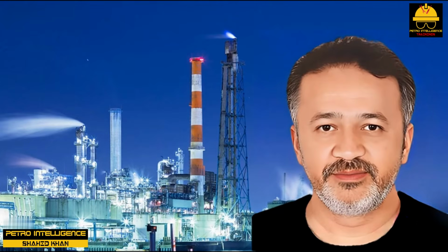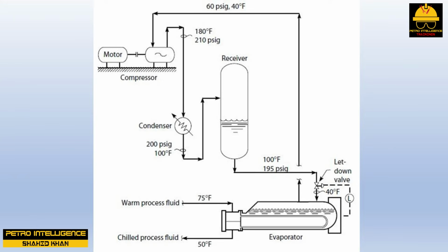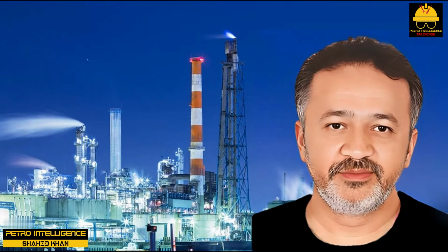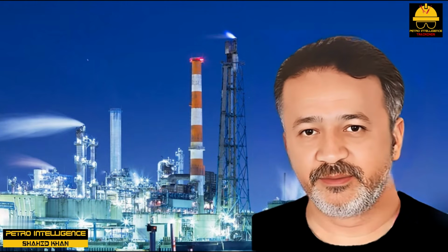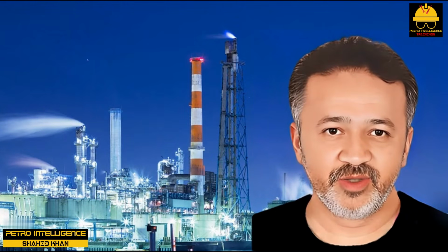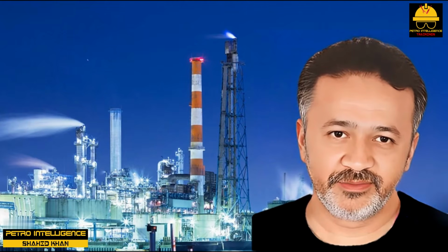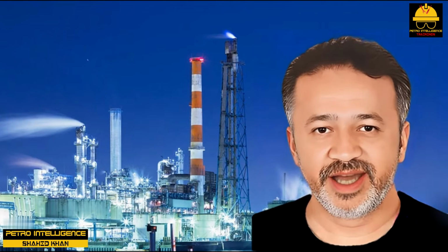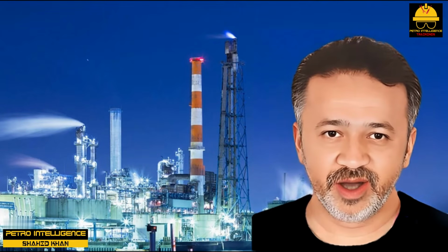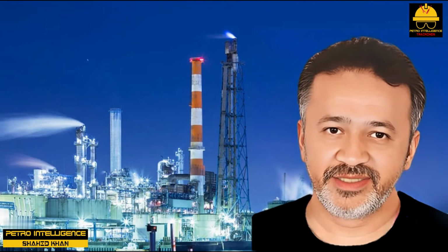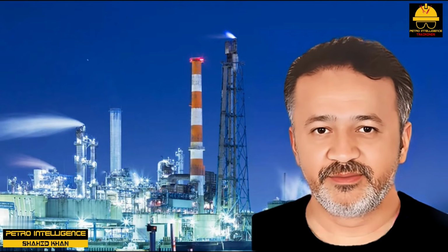Refrigerant receiver. Looking at the picture, the need for the refrigerant receiver is not immediately obvious. It does not appear to serve any process function. Many refrigerant systems are constructed without this vessel. However, it does have several important uses. For one thing, it provides a quiet zone for entrained lubricating and seal oils to settle out.